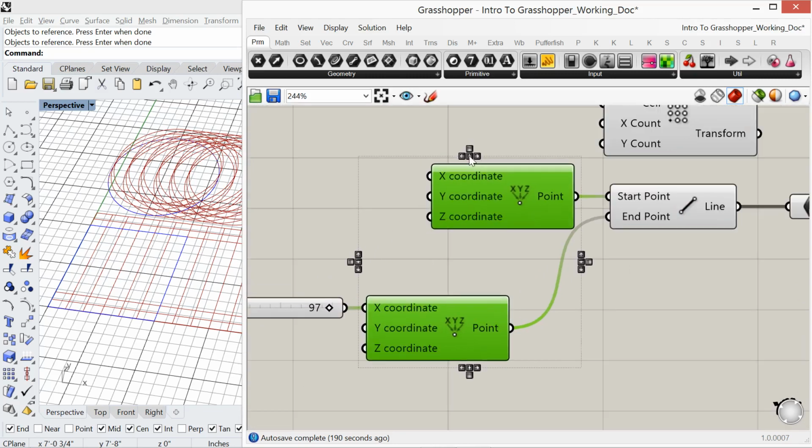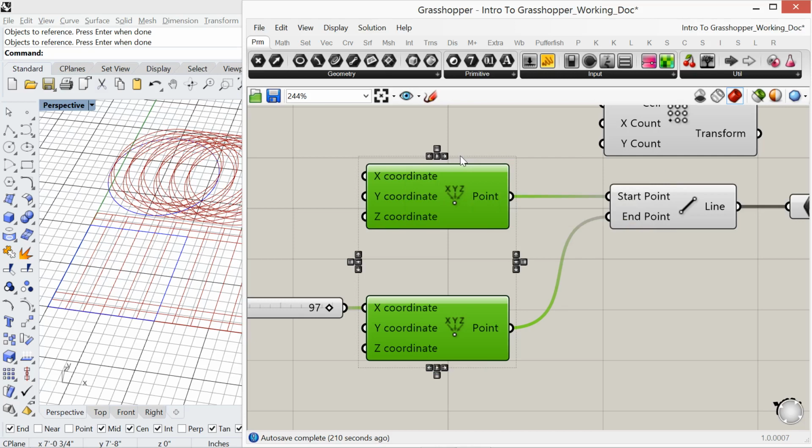Okay, what you see when I select them is the align window shows up, and I'm just hovering over, and you see the word align, and then you see Mr. Sparkle. Let's get to that in a second. This is getting back to David Rutten's sense of humor. I'm going to left justify. There's a left justify arrow that aligns those.